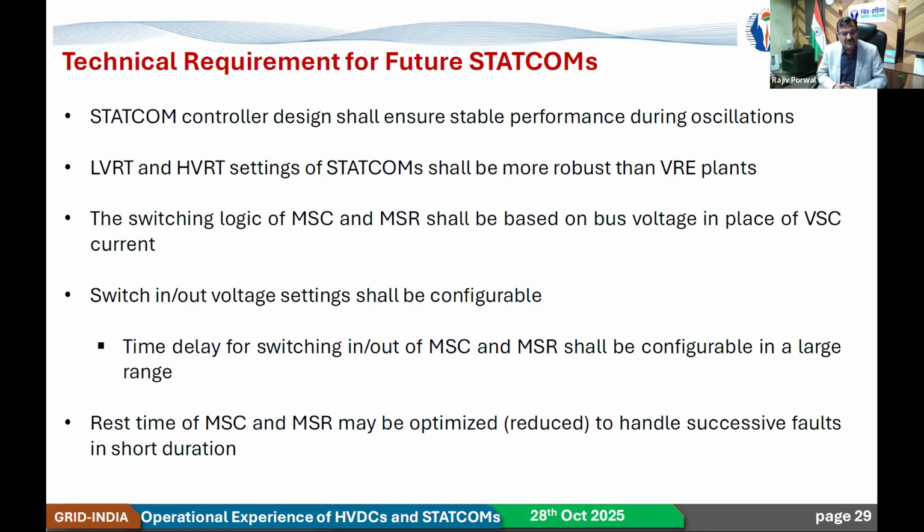Switch in and switch out settings shall be configurable. Time delay for switching in and out of MSC and MSR shall be configurable in a large range. Rest time for MSC and MSR may be optimized, reduced to handle successive fault in short duration.